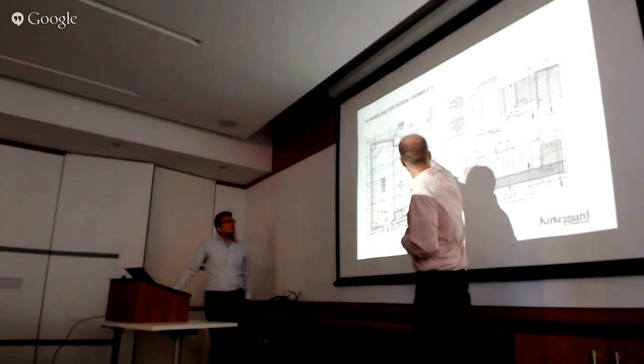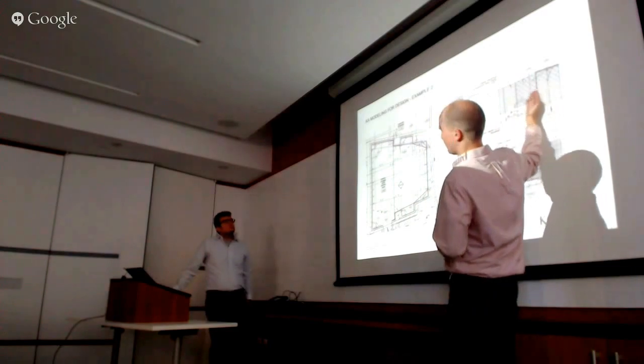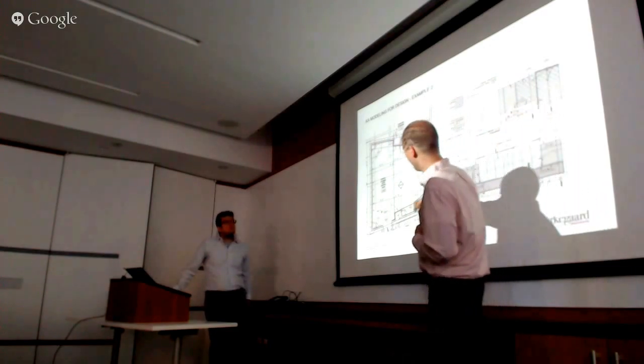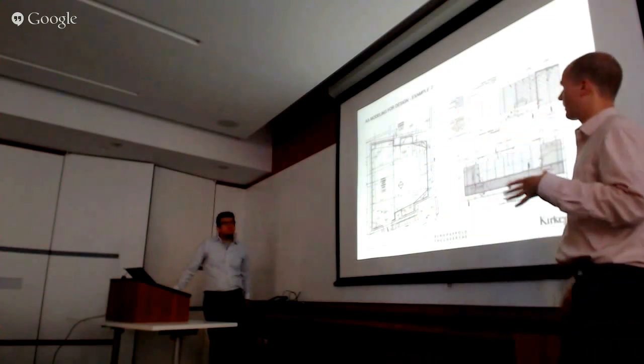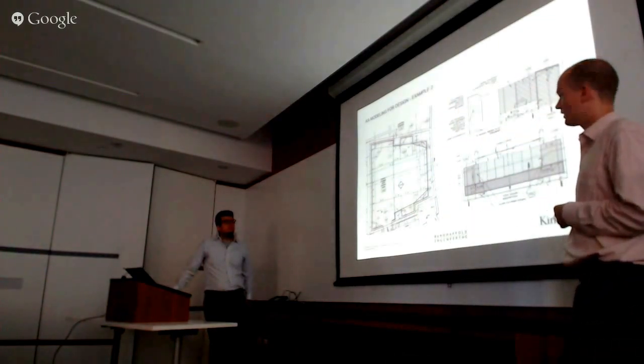Here is basically fabric wrapped absorption panels. What we've done at this middle zone is actually step the hard architecture back so that we're able to get a really large airspace and get some lower frequency absorption there.